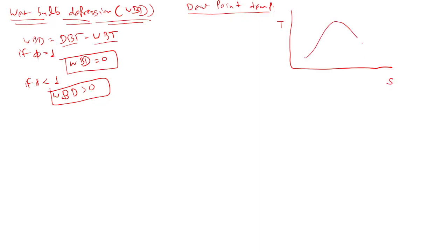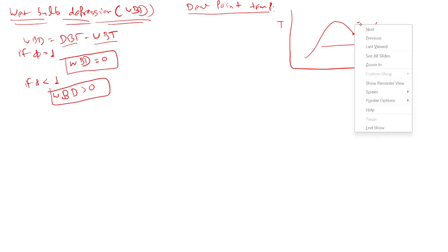Okay, let's suppose this is our initial condition of air, our initial temperature. Now we will cool it. Here also dew will form, right? Yes, sir. So is it the dew point temperature? No, it won't be. Sir, but cooling is along that inclined line where pressure is constant. You have to tell cooling along the constant pressure line, when dew will form, that is the dew point temperature.